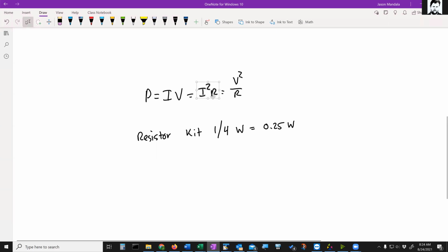If I lower R, for example, then I've made I bigger. Wouldn't you agree? And if I made I bigger and I is squared, that's going to dominate. So that's going to increase the power at a faster rate than R is going to be reducing it. If you lower R, you're going to increase I, and since you're squaring I, that's going to have a big effect. So you will be lowering this part of the term, but you're going to be increasing the squared part of the term at the same time. So if you have a smaller resistance, it's going to translate into more power dissipation in general.